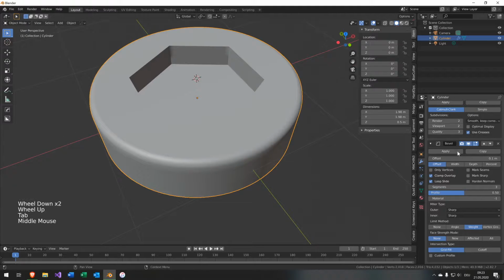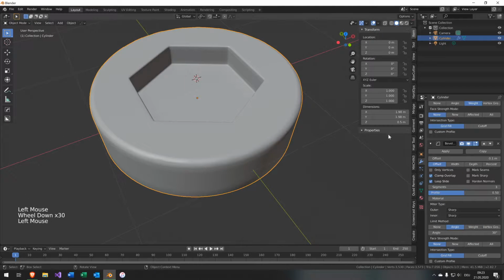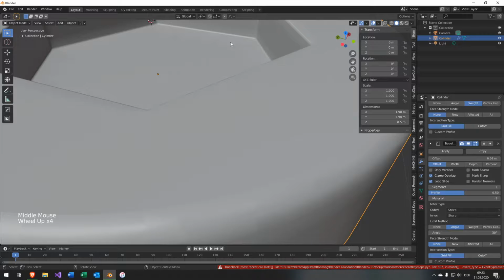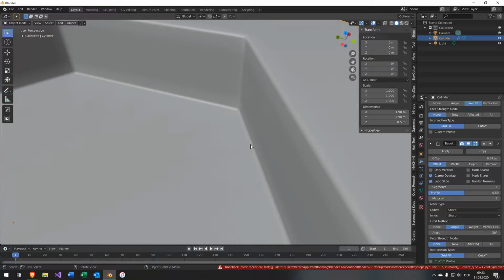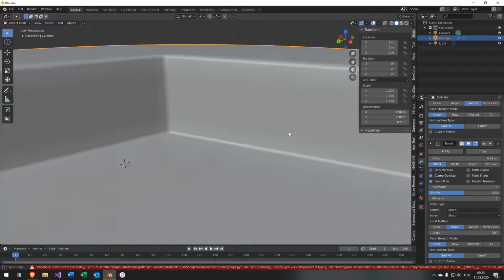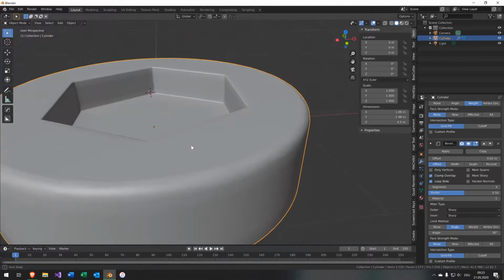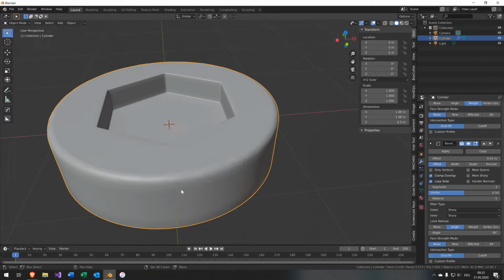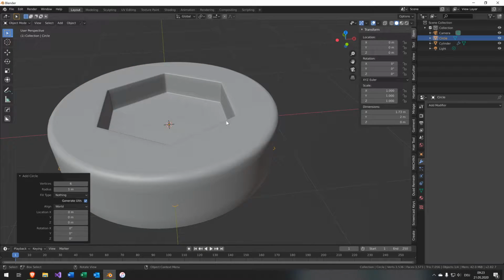And now I'm gonna duplicate this bevel modifier and set the mode to angle to bevel all sharp edges with a distance of 1 centimeter. And yeah, it looks pretty good. Just a small error due to pressing caps lock, but the edges are looking good. And what I'm seeing now is some sort of artifacts. Yeah, just have to make sure.